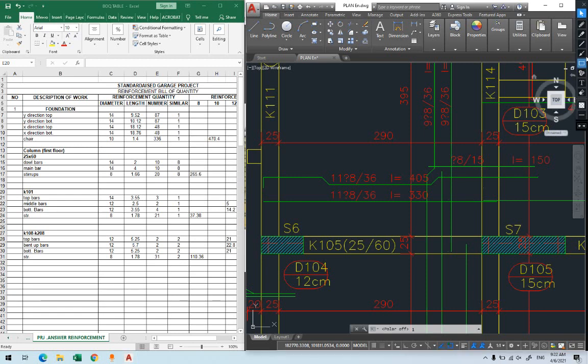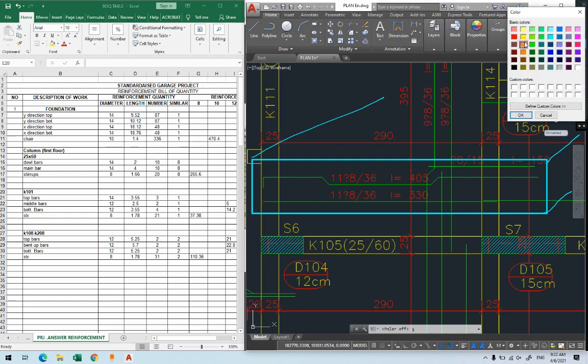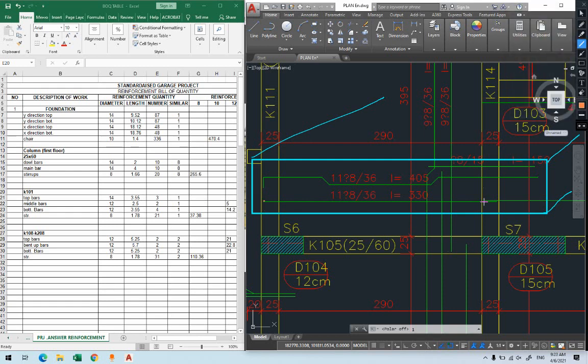As you can see, those are the reinforcement, we have it here. Again, the same way for slab, they will be provided like this, as if you're looking at the slab in this manner. Please remember. So what does that mean? This is the top, basically this is the bottom bar. Let me choose a different color. This is the bottom bar. This is the bent up bar, we have it here from the top, comes down and goes up. And this is additional at the top. This is at the top, we have it here.